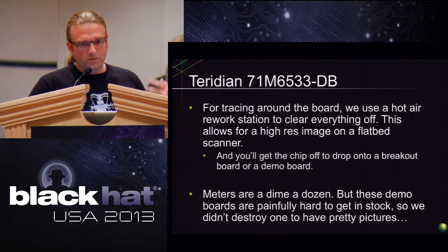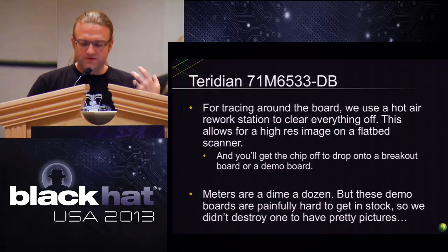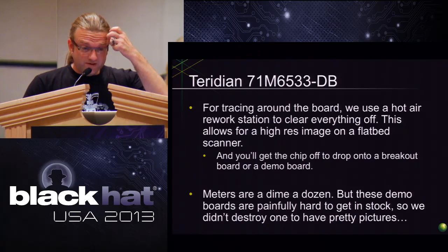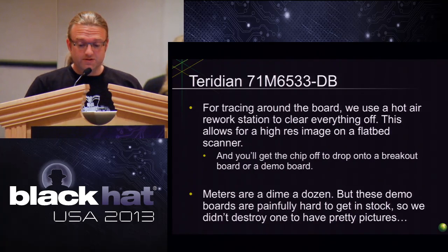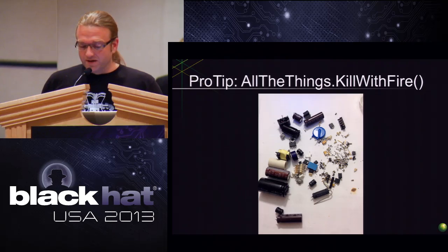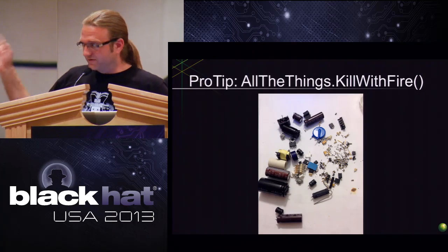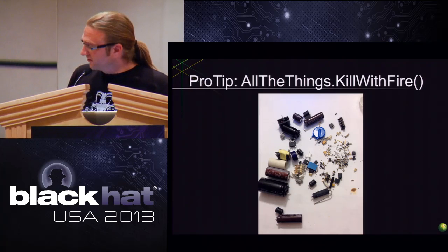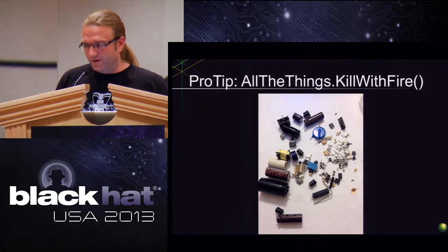Second thing, when you start wanting to look at these type of devices and how they work, you really want to figure out what the PCB is doing around the SoC just as much as you want the SoC. One of the tricks that we have started to do more and more is I take a production board and I desolder everything. That's all the detritus that was on the board. I'm sure it's important for it to run, but I don't care at this point. I take that, I throw it away.